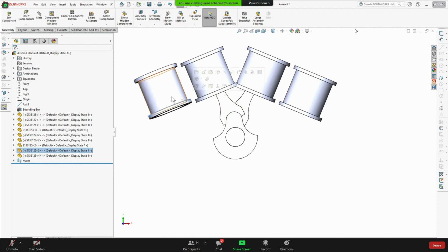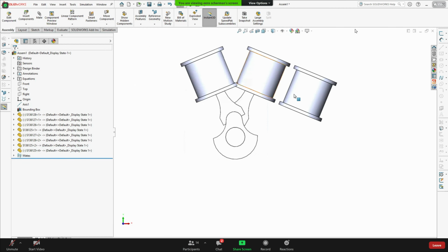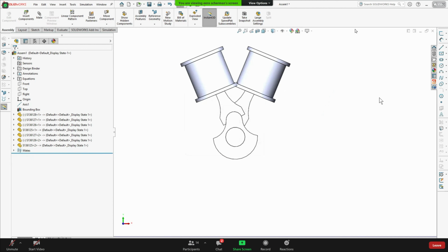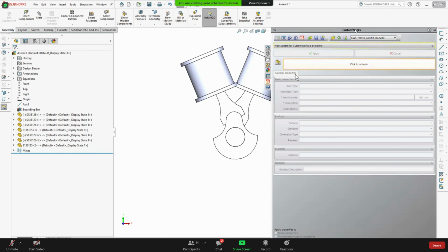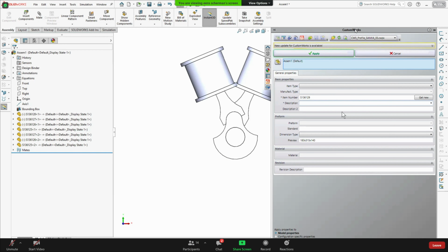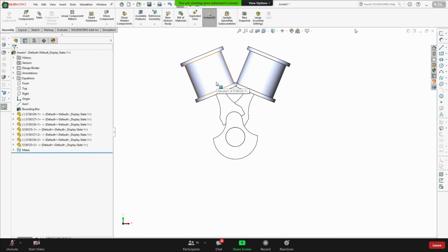Do you think it's a good idea from an engineering point of view? I mean, again, friction and all those properties. Well, it's quite a complicated and expensive type of motor, so maybe it has some benefits. The main benefit compared to traditional V motors, like the one shown here, which is a so-called V-twin because the cylinders are in a V shape and there are two of them, is that it's much shorter, half of the length, if we arrange the cylinders in a row.